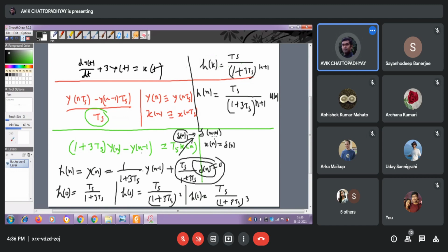Now there also this recursion will be equally applicable. Then everything will be shifted by the same amount. Your delta function is shifted, and its response is also shifted by the same amount. So n minus capital N, here also n plus 1 minus capital N, and here also u[n minus capital N].